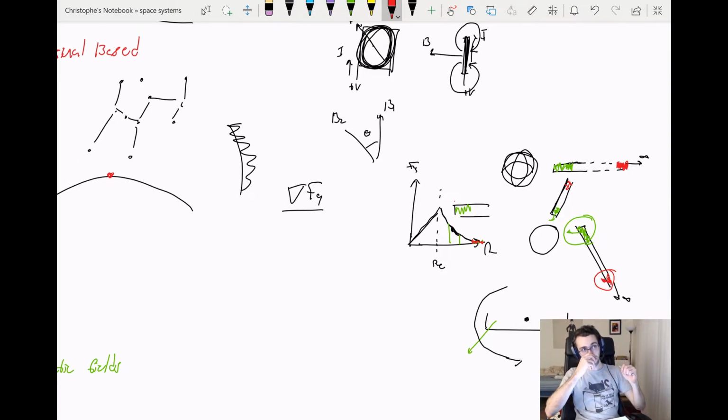Which just so happens to be when that infinitely long rod is lined up radially with the Earth. And what you can do is use that tiny force differential along the length of your space vehicle to shift your attitude ever so slightly in orbit. It's not an active control measurement, and sometimes you don't really want it at all.